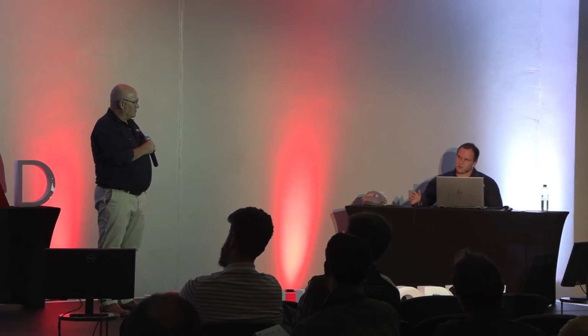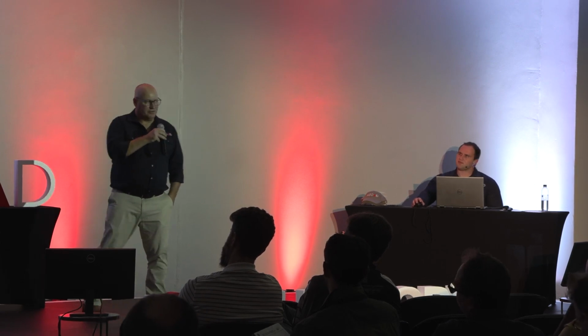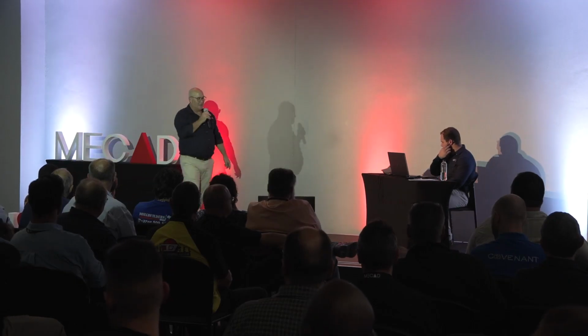I'm going to show you guys another thin feature option you can use. Like we said, you can use either the extrude or the cut. So Edith, how many ways can you cut with a thin feature? Who of you have cut with a thin feature? Okay, there's a few hands. What is the default behavior when I create an open contour? Rocco showed us, he had an open contour, he said extrude, default is then a thin feature, makes sense. What's the default behavior with a cut if I try and cut with an open contour? It's cutting with a plane. Somebody said that.